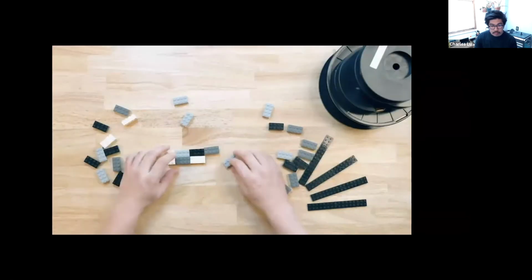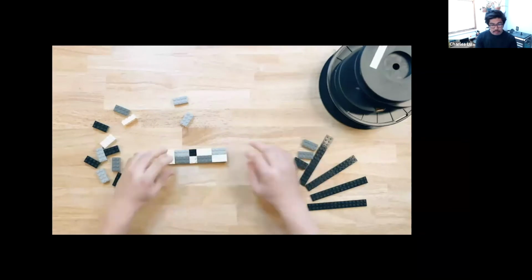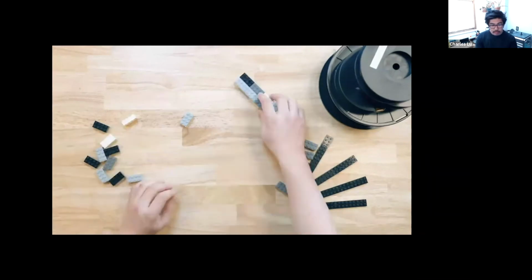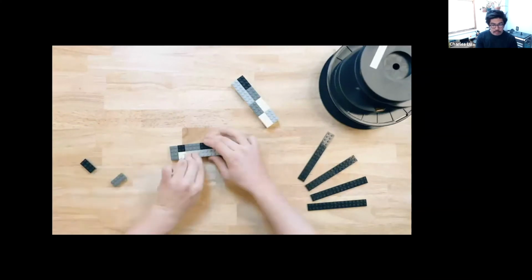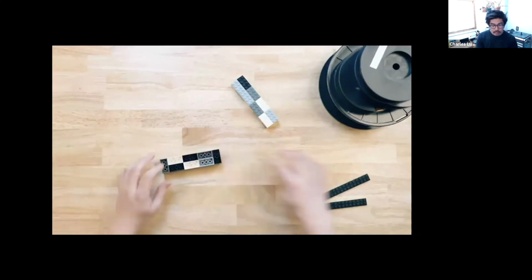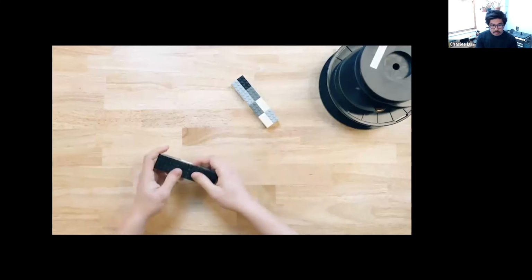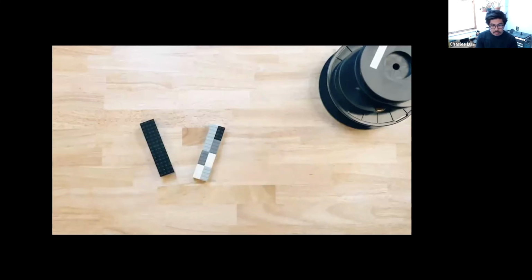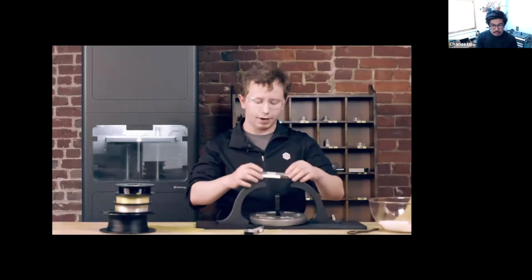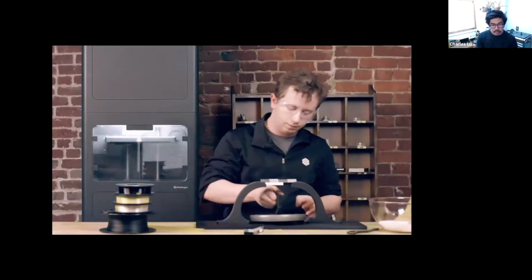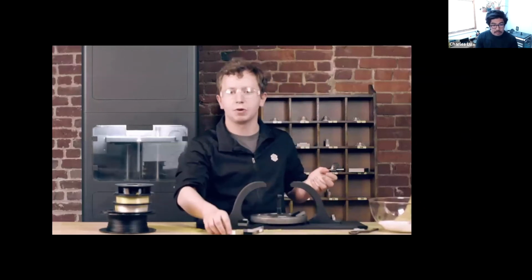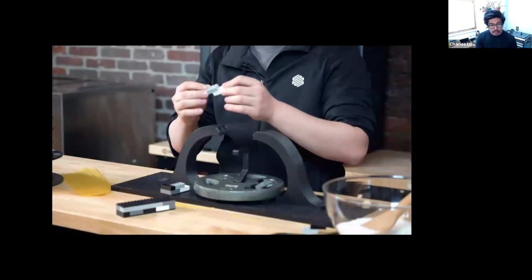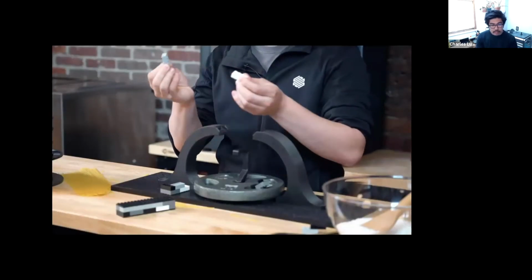So chopped fibers are basically a bunch of little pieces of a strong material adhered together in some way, like how these bricks are held together by their connection points. A continuous fiber takes that same material but forms a continuous connection across the loading surfaces of the same part, represented by these plates on the top and bottom. So when we apply a load to a chopped fiber part, it breaks at the connection points, which when applied to printing composites is just the thermoplastic holding it all together.